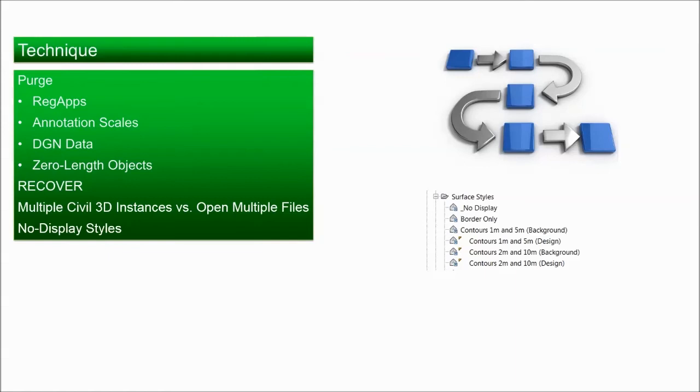If instead you choose to use styles that turn the components off, forget about layer freezing, we're using a style that turns things off, that will give you a bit of a performance boost, and it'll actually make your drawing a little bit smaller as well. So instead of freezing layers, consider using no display styles.